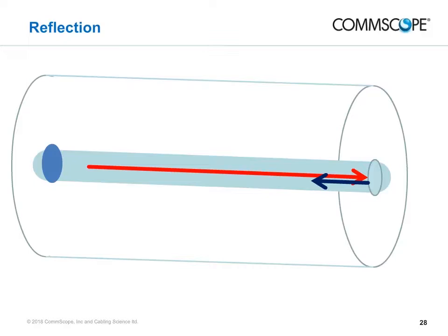Reflection in a conductor has several field implications. For example, when connectors are corroded or improperly installed, there will be an impedance mismatch that will increase reflection and degrade signals to the subscriber.